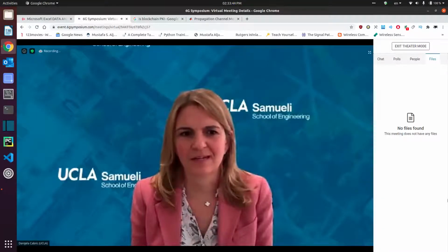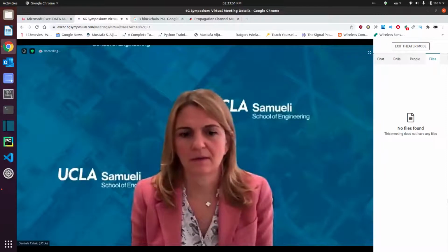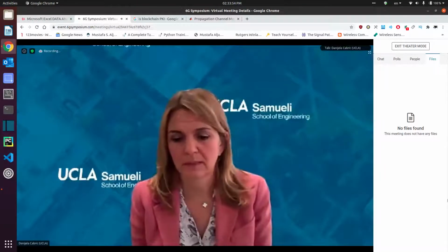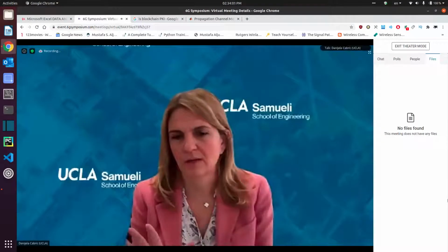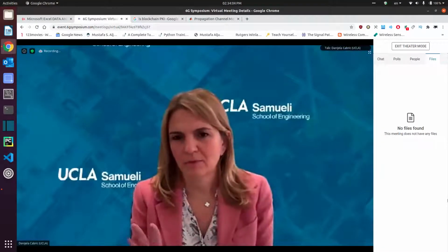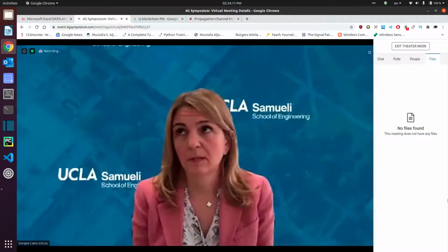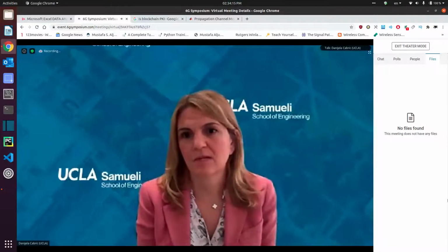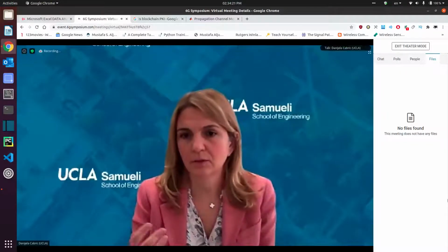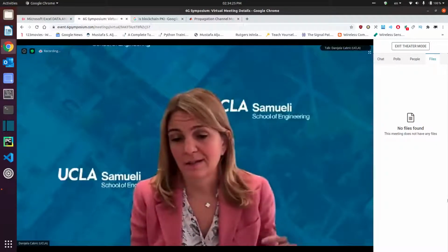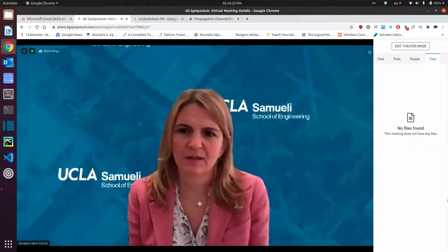And I'll give you a recent example on exactly the problem that Tim mentioned on beam training in millimeter wave networks, which is, as he says, a very difficult and time-consuming problem, right? If you look at what machine learning is trying to do, it's kind of model compression in my mind. It's trying to take a very complex problem and have a more compact representation. At the same time, from physics, we know that millimeter wave channels are sparse. So there is that physics sparsity that we can actually put on top of machine learning's ability to compress. So we've tried this, I call it machine learning assisted compressive beam training, in a very recent paper.